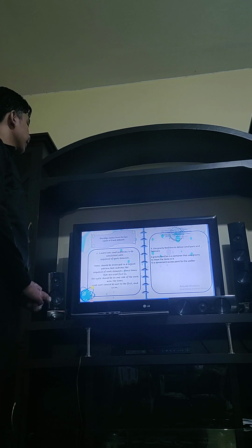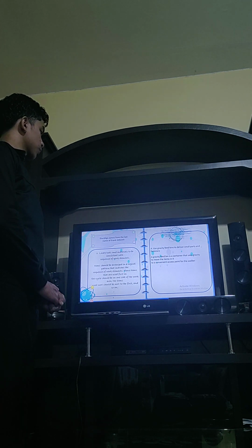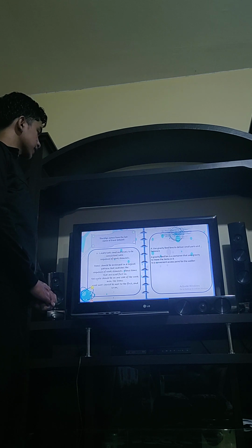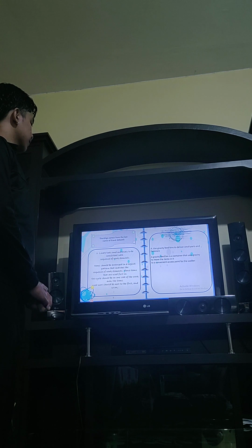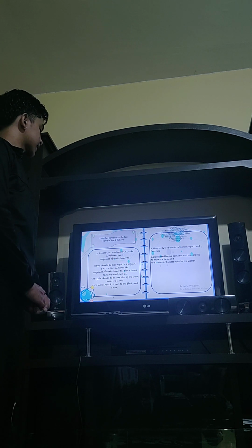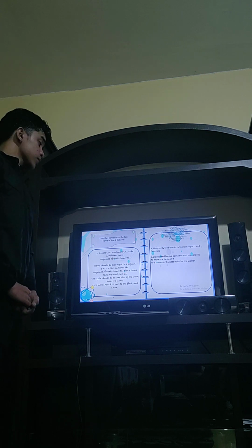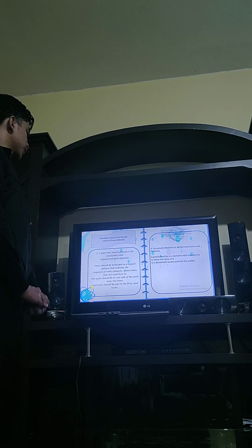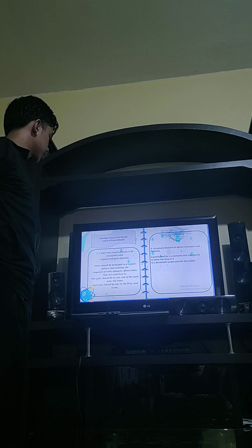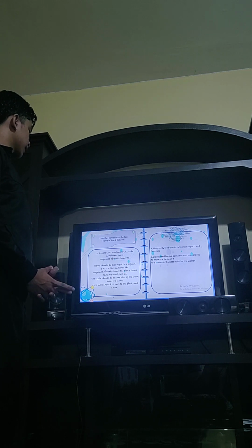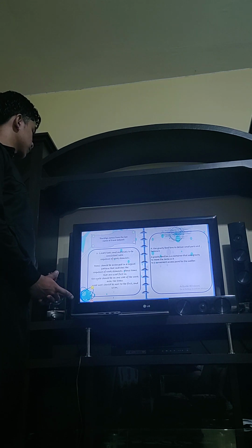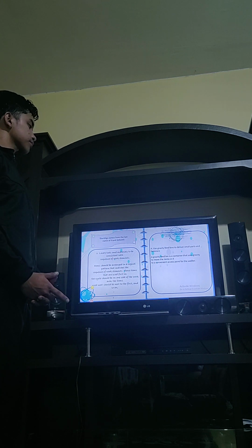Number 3, locate tools and materials to be consistent with the sequence of work elements. Items should be arranged in a logical pattern that matches the sequence of work elements. Those items that are used first in the cycle should be on one side of the work area. The next item should be next to the first, and so on.